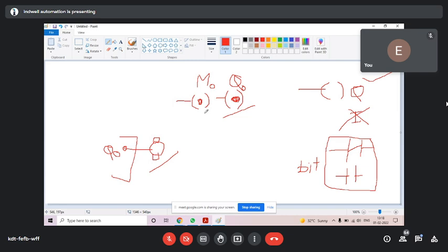Did you understand the difference between these two, flag and output? Yes, in coil we can use flag and output address. That is the thing I understand. So one more thing you should remember, that difference: if output is on in your program, it has physical existence. Outside PLC you have something, motor, fan, lamp. And if flag coil is on, then nothing is on outside.